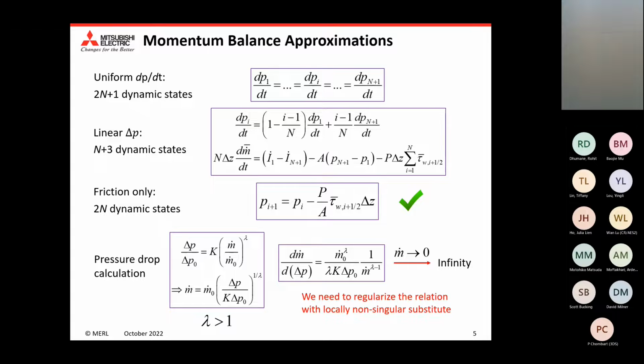We just assume that the pressure loss is a function of the mass flow rate, and we ignore other effects, for instance, the quality and density. Then we can do curve fitting for these two constants, because these two constants are generated based on the pressure drop correlations.